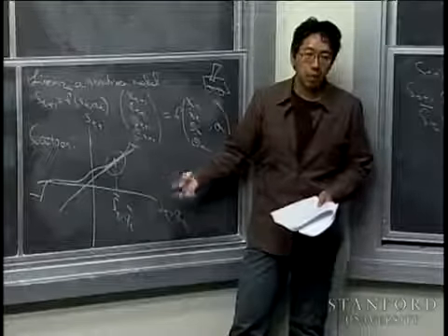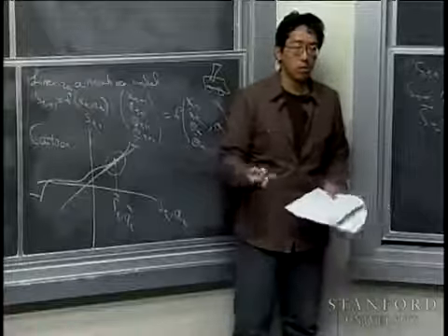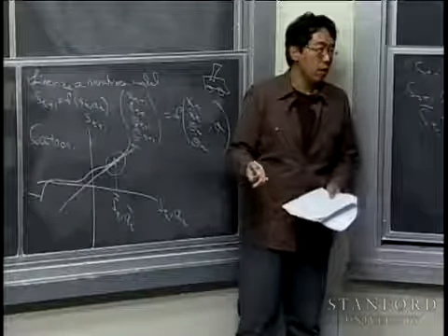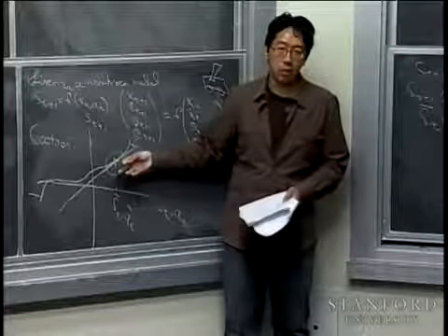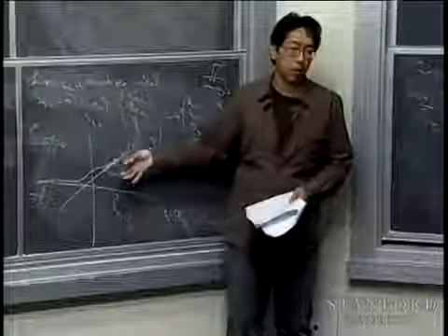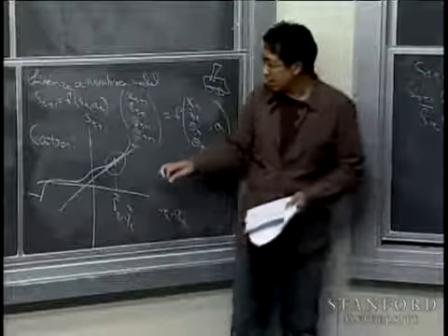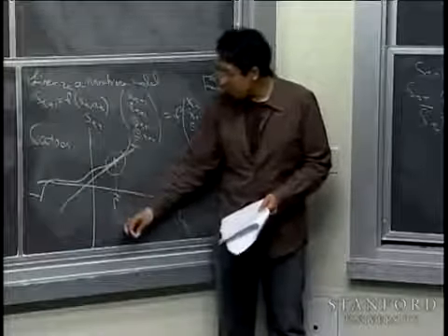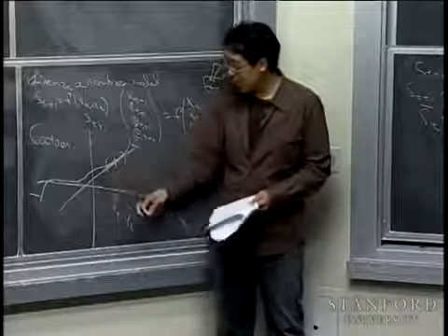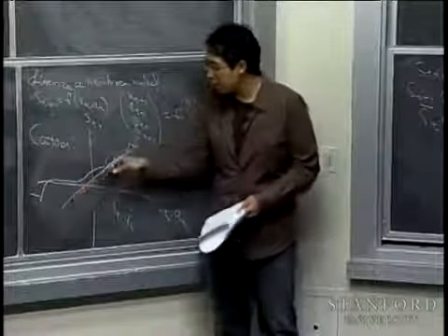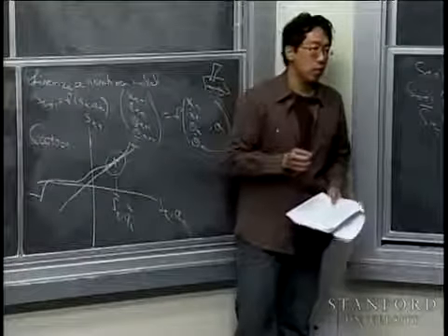And so one rule of thumb is to choose a position to linearize according to where you expect the system to spend most of its time, so that the linear approximation will tend to be an accurate approximation in the vicinity of the states that you actually expect to see the most often. And just to be clear, this is about choosing the point S bar, A bar, that we'll use to come up with a linear function that we'll pretend is a good approximation to my original nonlinear function f.